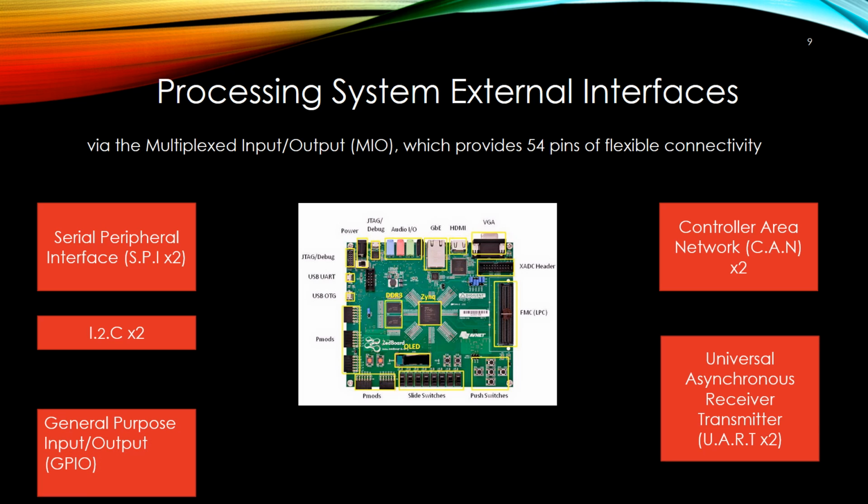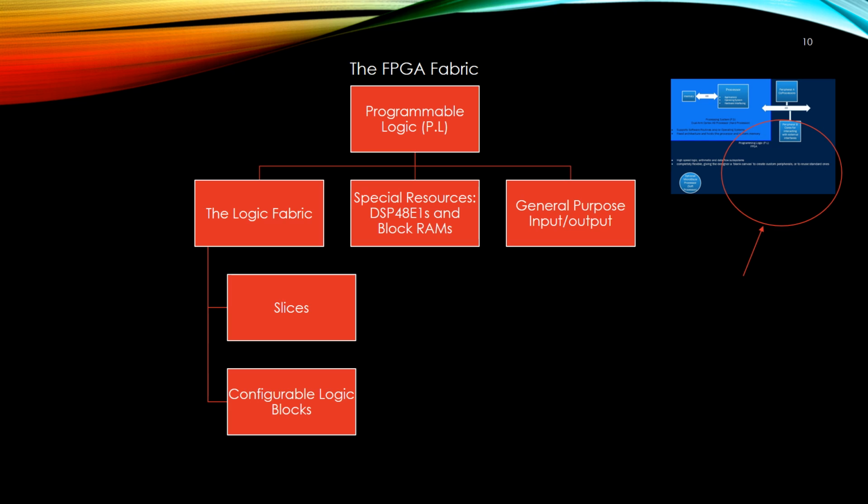The general-purpose input-output has 4 banks of GPIO, each of 32 bits. The SD is used for SD card memory. The USB is used for Universal Serial Bus and is in compliance with USB 2.0 and can be used as a host, device, or flexibility. The Ethernet MAC peripheral supports up to 10 megabits, 100 megabits, and 1 gigabit. Programmable logic is based on the FPGA fabric.